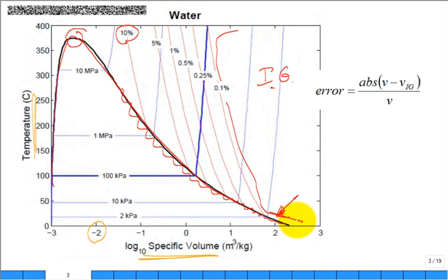And that's really a startling result when you think about it. Really? It's ready to condense, and yet the water vapor still behaves as an ideal gas. And that's how moist air is. It has water vapor, and it behaves as an ideal gas. So this justifies that ideal gas approximation. How many people were probably troubled by that? You thought, does this really make sense? Even saturated air, close to that liquid forming, that water condensing, yes, it's true. So this plot is done to scale. I think I did it in MATLAB, and it took me a long time to do it, but it's true data, okay? All right, let's press forward.